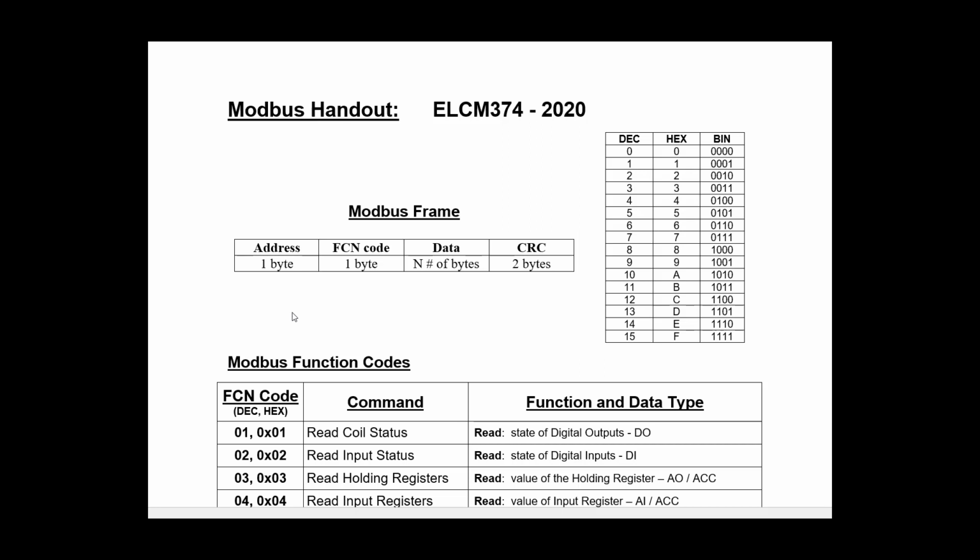And if you recall, at the beginning of the presentation, we talked about the 4 main fields of the Modbus message, or the Modbus frame. Notice how here it's indicating the address field, the function code field, the data field, and the CRC. The CRC stands for cyclic redundancy code, and this is a very popular error checking that's used in network communications, for protocols that run at all the different layers on the OSI model, and for both DNP3 and Modbus.